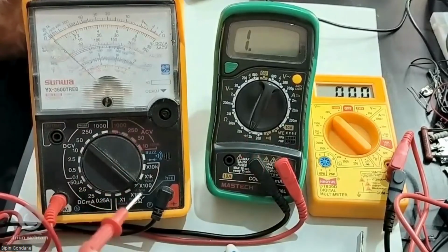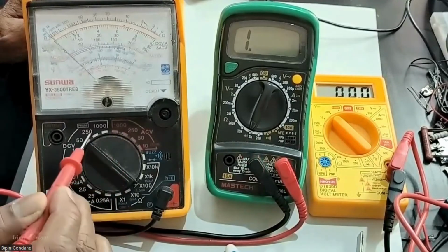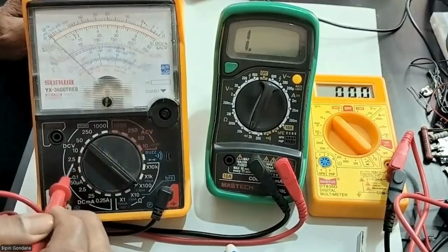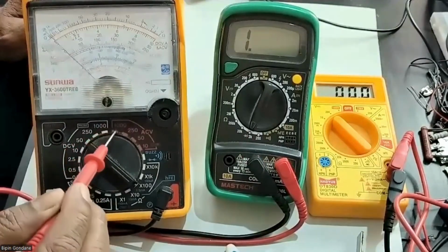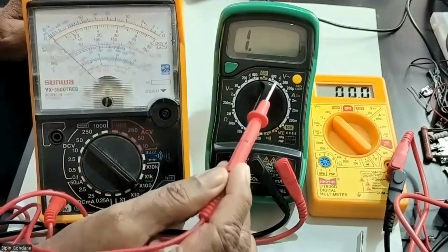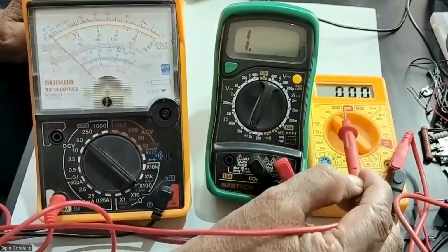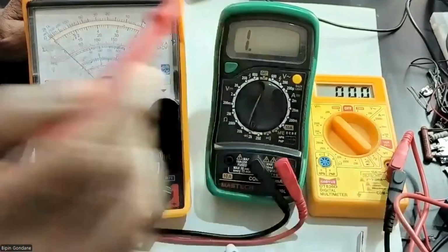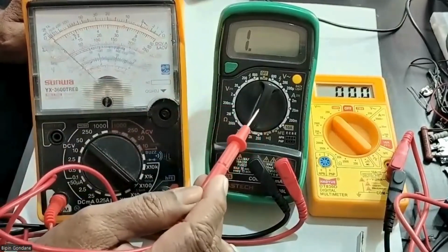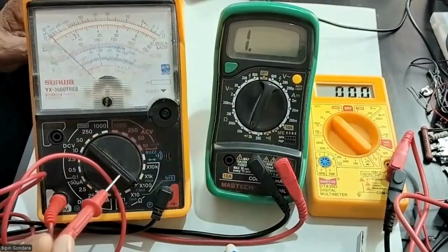Please remember, very important point, when you are measuring AC voltage or DC voltage, which is this side. So you can see this is DC voltage and this side it is AC voltage. Both sides. This is AC voltage over here and this is DC voltage over here. Here also the same, AC and DC. Okay. So please remember, while using, you have to select this switch properly. That means while measuring AC, you don't put it on some other values.